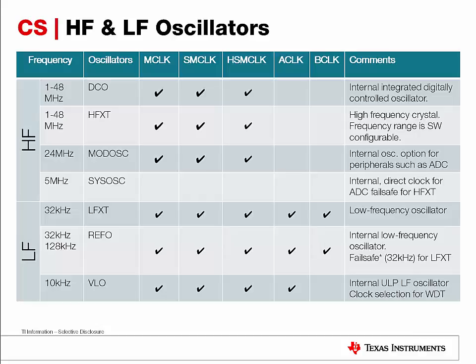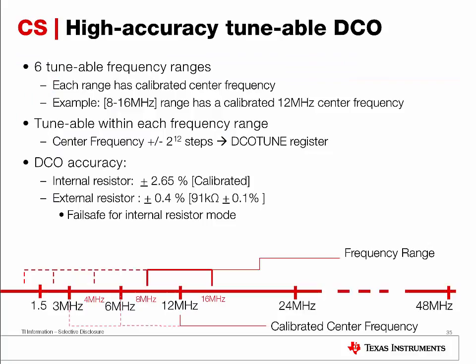One particular clock source that we would like to cover in more detail that is unique to MSP432 is the DCO. On a typical DCO system, the user can select from a number of pre-calibrated frequencies, and these pre-calibrated frequencies are usually pretty accurate, even across temperature and voltage. However, if you need to come up with your own frequency that is not one of the pre-calibrated values, it is also quite difficult to do so on a DCO system, which typically requires calibration that needs to be done at production. So the DCO of the MSP432 introduces a new way of doing on-the-fly calibration.